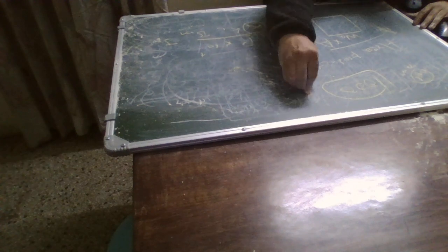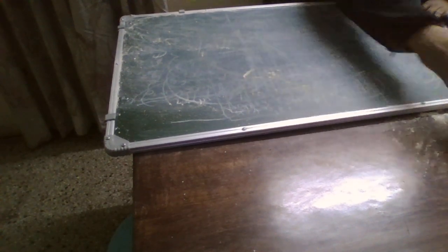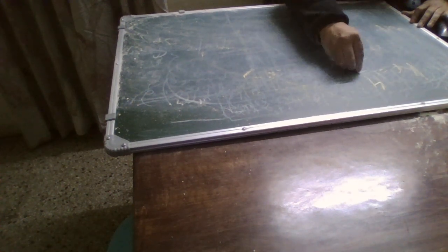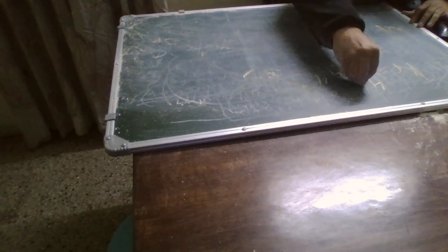Again, if you see, it's those who say, okay, what does it matter by 0.1, 0.2. You see that this Kf, which is the waveform coefficient for a square wave, is 4, whereas for a sine wave it's 4.44. So again it's a 0.44 difference only, and so the other thing that we have to see is basically its relation with the given temperature rise.